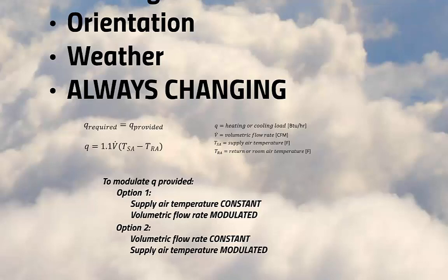The terms CAV, constant air volume system, and VAV, variable air volume, are referring to the total airflow moving through the system. There are CAV configurations in which the total airflow in the system is constant, but the airflow that goes into the various spaces is modulated. And there are constant air volume configurations which modulate the supply air temperature being sent to each space, all while maintaining a constant airflow to the space. This might sound a bit complicated, so let's look at a couple of these different configurations of commercial-sized constant air volume systems to see how this all would happen.